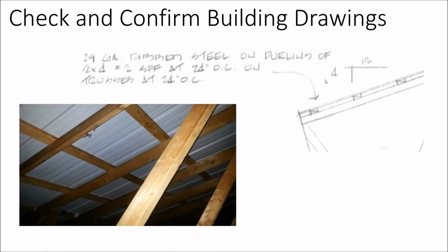Collecting whatever building information you can from the client helps the project go along. I like working in commercial because you often have access to building design documents that you might not get in residential. I was evaluating Half Moon's building a while back, and I saw it's a 4/12 roof pitch, and that's cool. It's 29 gauge steel, but it looks like they're putting a metal roof on top of horizontal purlins before going onto the rafter. I hadn't seen that roof design before, but they were able to get up into the attic and snap a picture, and that confirmed for me what's going on.